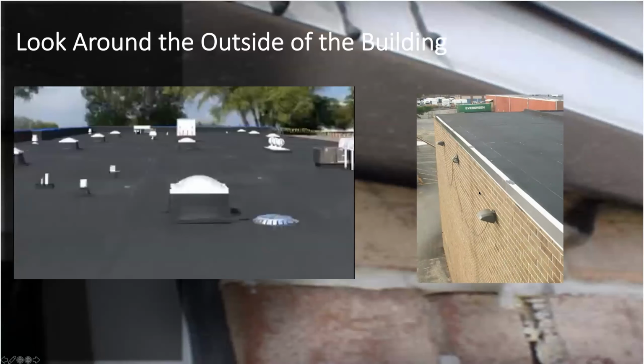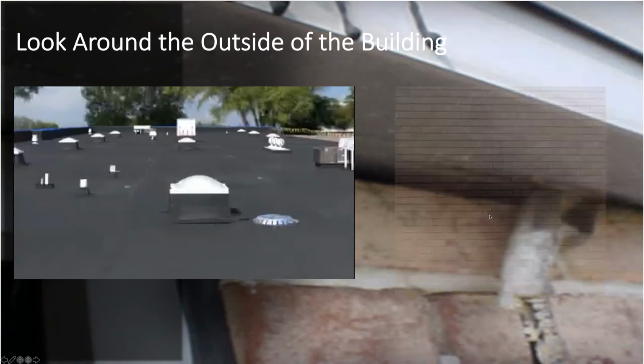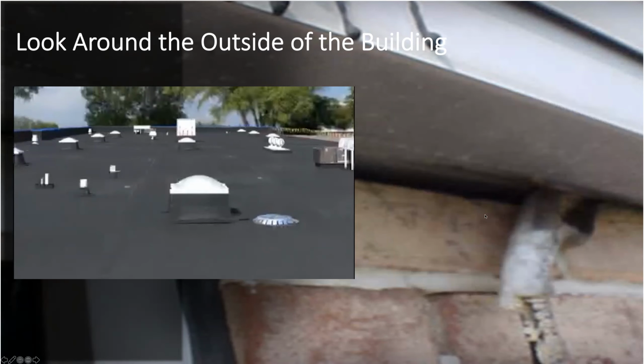Here we see some stains coming down the side of a wall. Not a very good photo, but there's probably something going on at the edge of this roof where it's allowing water to get into the system. A lot of times mortar joints fail, also take a lot of water in, and the roof's blamed. And here's a better picture of that wall that's staining. There's trapped moisture in this wall that needs to be taken a look at, again, once you're up on the top of the roof.